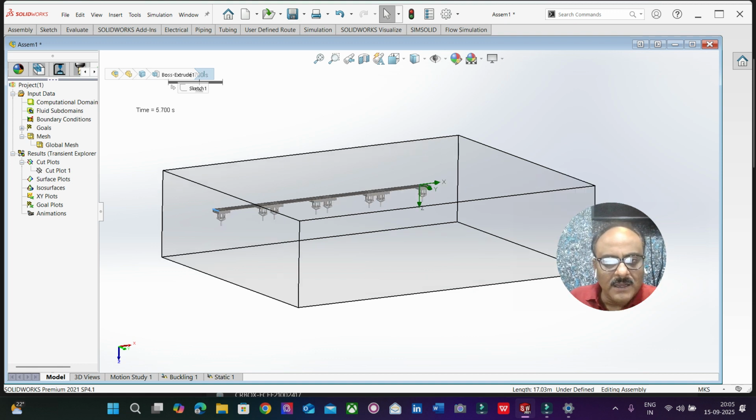So here, instead of finite elements, we are going to split it into cells. We call it a boundary element, and these boundary elements are finite volumes. We can split it into cubes or cuboids, and these cubes or cuboids can be called cells. In this case we are going to have immiscible fluids. Air is a fluid and water is a fluid, so there will be certain cells that contain air, and some cells that contain water.